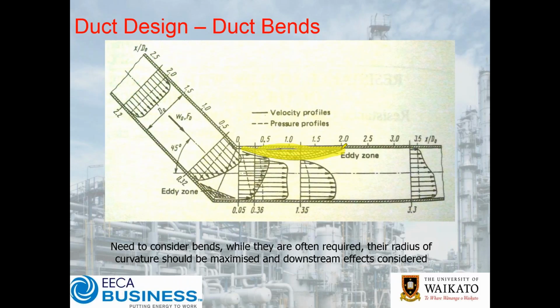Now of course what happens is, I'm just going to change to my spotlight here. If our flow and everything else is down here, then we can get away with this by and large. It's not going to cost us a huge amount. However, if because of space constraints, our fan inlet is right here, or even worse, perhaps right here, we can have quite a big gap in our intake to our fan and cause all sorts of issues and challenges.